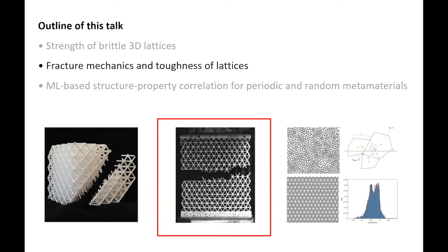But then, here's the question. You have your 3D model, so you can look at the entire stress. You show some contours of the stresses, I believe. Right, they are fully triaxial. Why are you focusing on tensile strength when, in fact, the solid is not under any axial tension? It's in fact under a triaxial state of stress. So I'm a little bit surprised that you are only referring to two scalar values. Maybe how about shear strength?